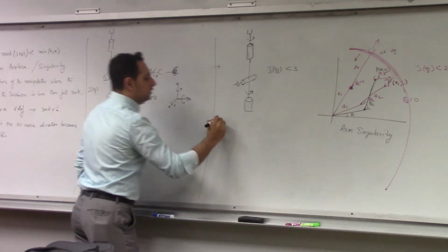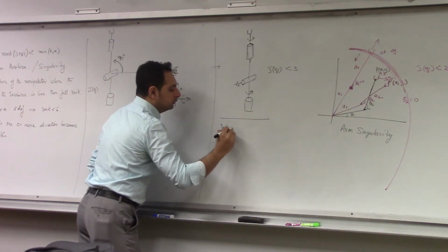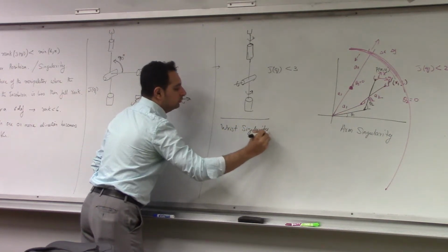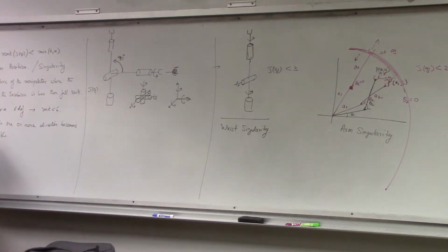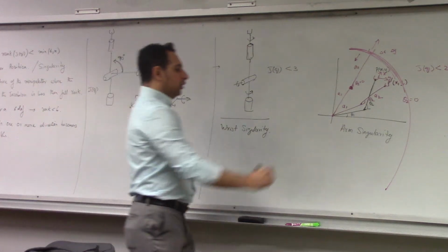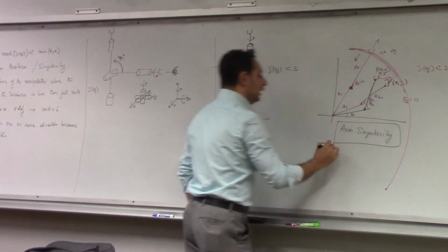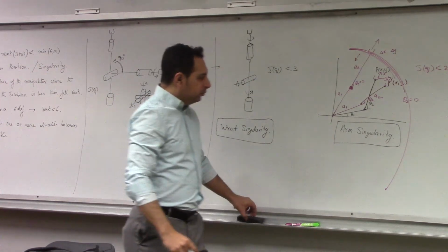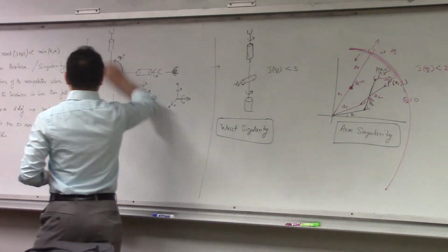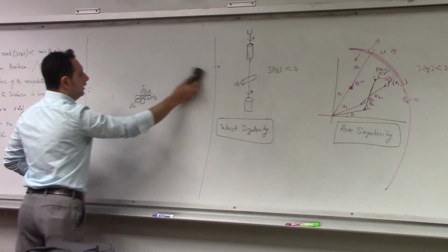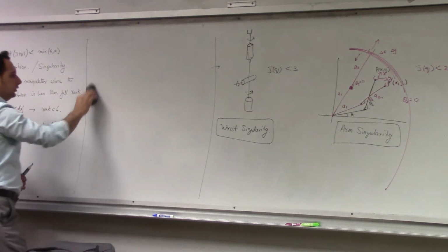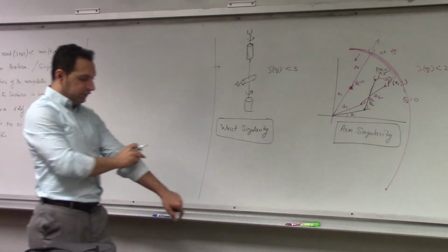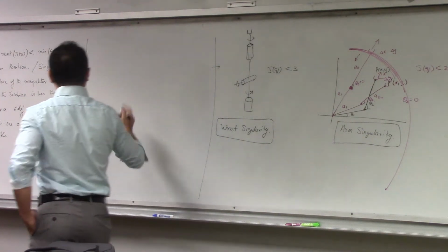This is called a wrist singularity. So you can find out at what points orientations are not possible, and you can also find out at what points in the workspace the positioning part becomes impossible, that is, generating linear velocities along x, y, or z. Now, how do we find a singularity? What is the condition for detecting a singularity? So the necessary and sufficient conditions.